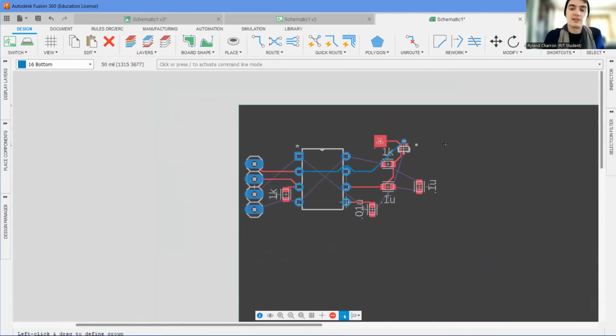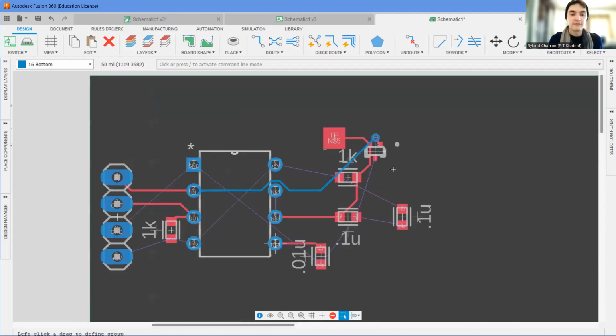So you'll often see ground pours in your designs, because having a ground pour or a ground plane is actually a really stable and efficient way of doing a ground for low current signals and for DC signals especially. You typically don't want high current and high current AC with logic to have the same ground. So you would do separate ground pours for those. But those are all more advanced than what we need to get into today.